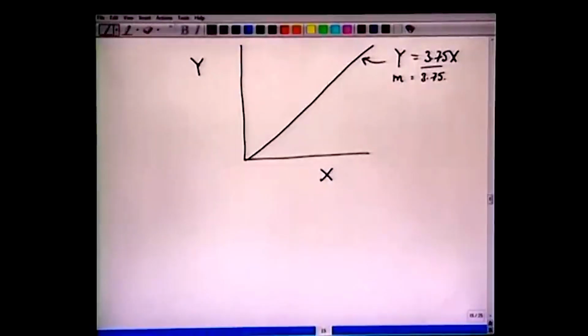Okay. Let us mark down the points, go back to this stage again. We have two streams getting in here: y0 for the pure solvent is 0, and this is x0 which is given to us. So, we can mark it here. This is x0 and y0 is 0 here. This number x0 we know, 0.1765. So, that is a mole fraction, solid-free basis in the feed.